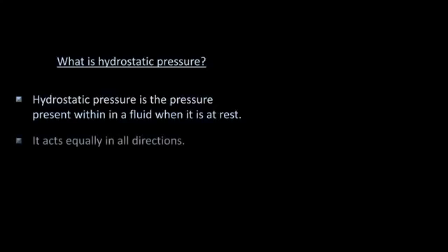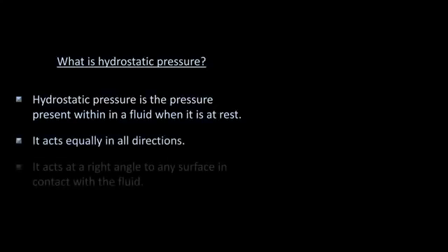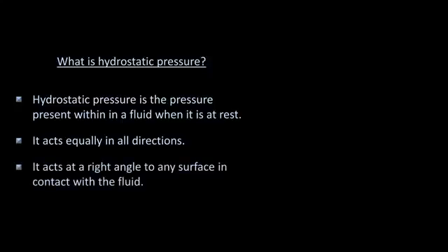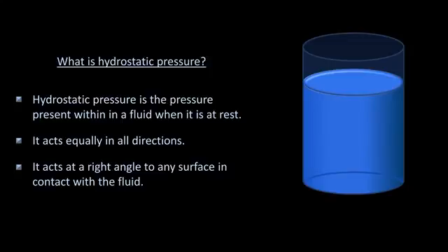It acts equally in all directions, and it acts at a right angle to any surface that is in contact with the fluid. So if we have a glass of water, at a given level within the water, the hydrostatic pressure, which is a result of the weight of fluid above it, acts on the side of the glass equally in all directions.